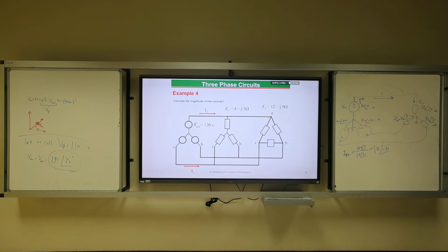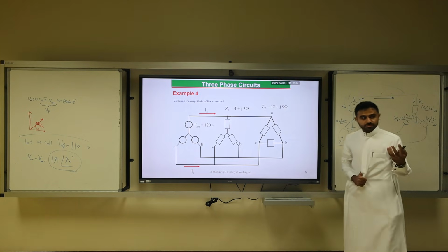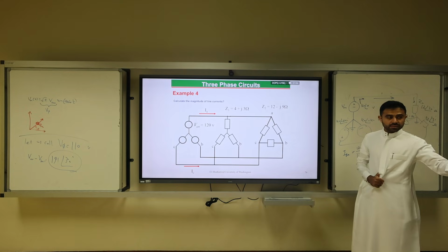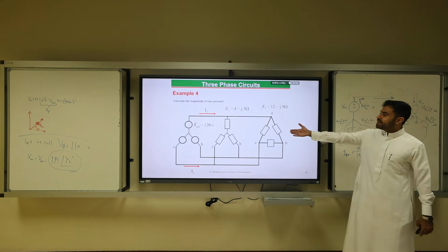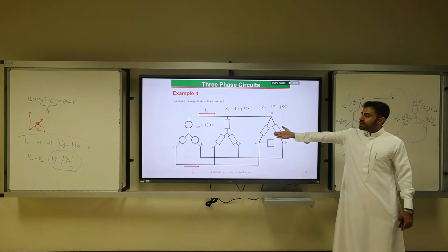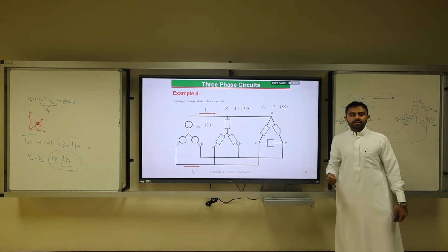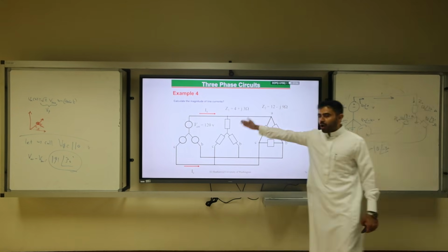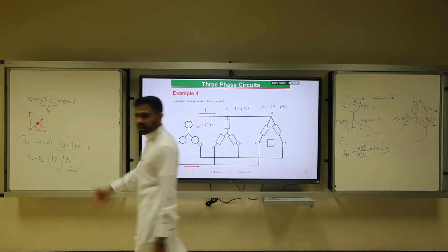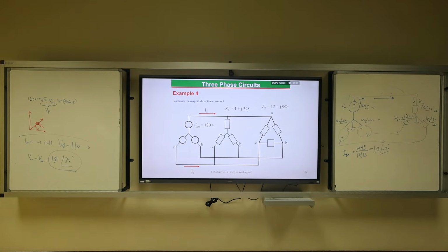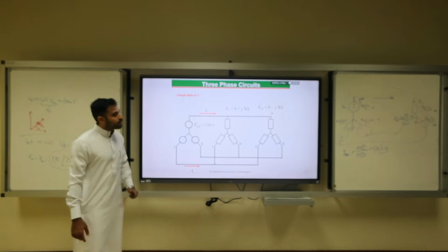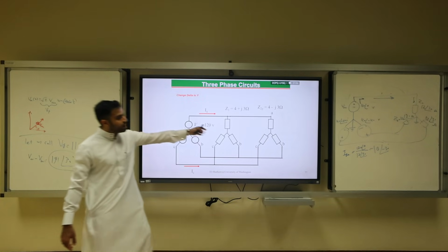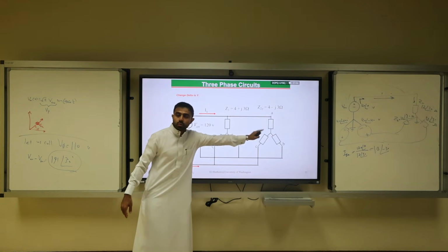What if I have two loads? Should we panic? No, because I can easily divide this by 3 and get 2Y and find the parallel combination. So a good strategy to solve that, if I have one Y, one delta, is I unify everything and make them Y to Y. This is the first step. Convert this to what? Y.